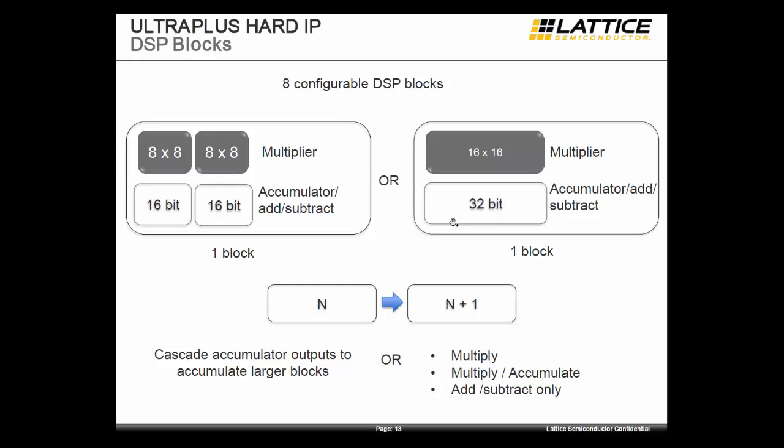Now, the configuration of this DSP block is based on an instantiation that is available in the tools for iCE40 ULTRAPLUS, and you can either build a multiplier, multiply, accumulate, and/or add, subtract only functions.